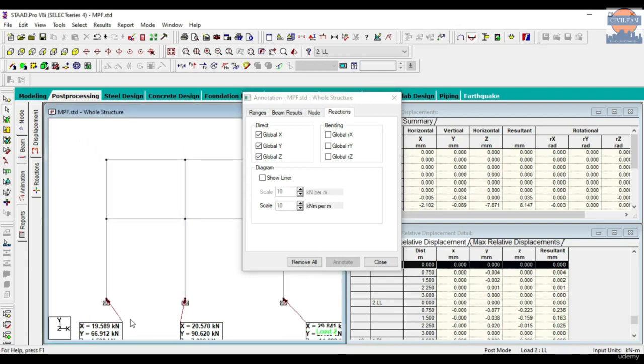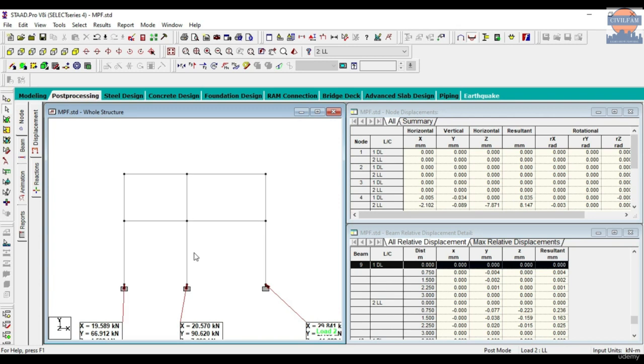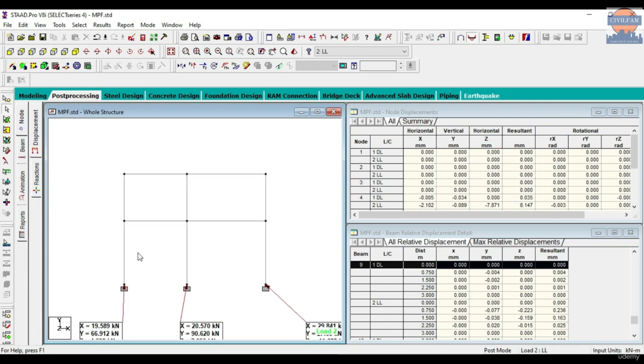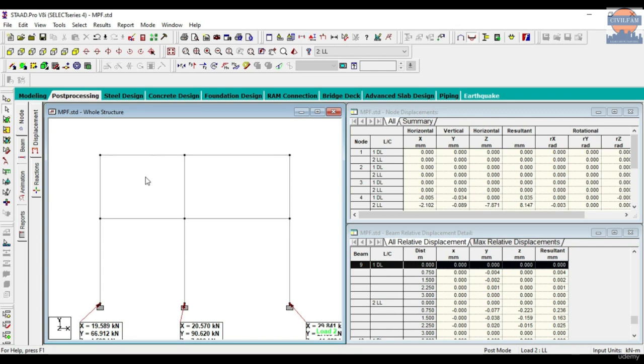These are the values that I basically check when I am doing my foundation design. How much load I'm getting in y direction, because that's my vertical direction. Axial forces, how much amount of axial forces I'm getting, I'll check like this, and then I'll show you how to do all that in the future classes. So like this, you can not just model but also put the loads and analyze your portal frames.